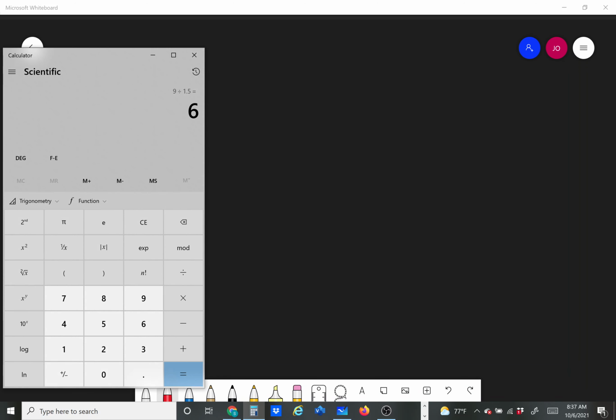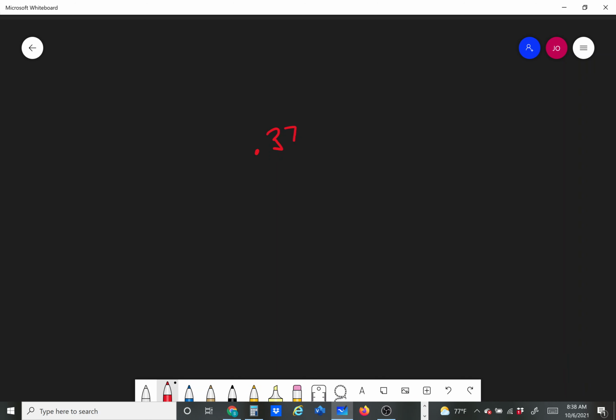So we know that our power is half a horsepower. So we're going to punch up our calculator again. And we know that 1 horsepower equals 746 watts, or at least I hope we do. So 746 times 0.5 is going to give us 373 watts. I want to get this in kilowatts, so I'm going to divide that value by 1,000, and that is going to give me 0.373 kilowatts. All right, so I have 0.373 kilowatts is what this thing is running.